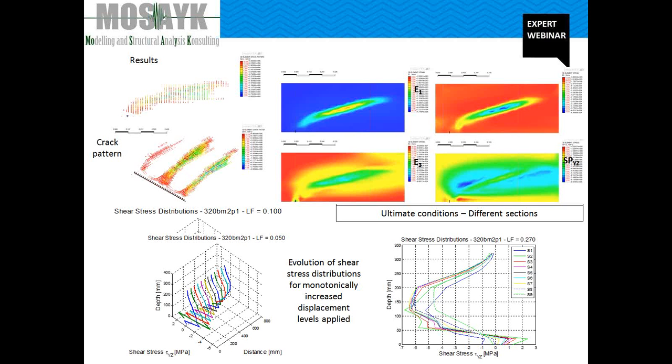A brittle web shear failure mechanism results from an inclined diagonal crack. This can be observed using the total strain crack approach, which for this specimen, with a sharp web width variation along the depth, almost linearly propagates from the support to zones higher than the centroidal axis, at a distance of about 2 cross-section depths. This was possible due to the capability of the total strain crack approach in Midas FEA.